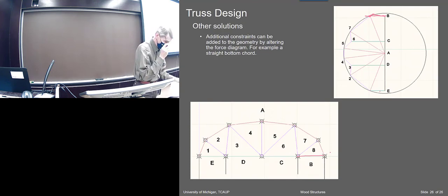And then once you get the size of the member, maybe it even gives you on here the weight of it, does it? Yeah, it does. Look at that. It gives you the self-weight. So you don't have to do a lot of calculations. Between this table and your graphic statics, you should be able to design it and get the weight. And the goal of the game is to get one that's a little bit lighter maybe than 676.6 pounds, right? So you can see if you can do that.